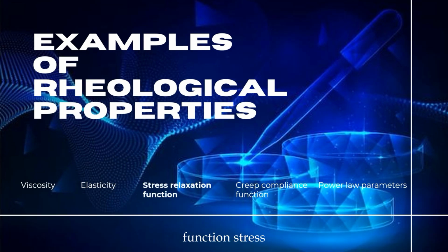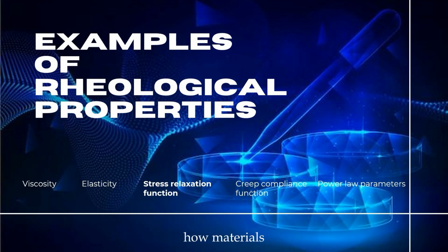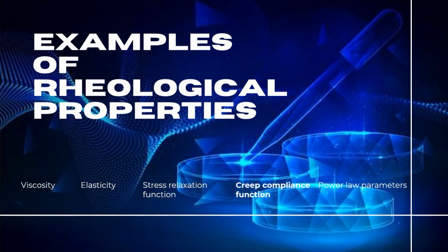Stress relaxation function. Stress relaxation is a key concept in rheology that describes how materials relieve stress under constant strain. When a material is subjected to a sudden deformation or strain and the strain is held constant, the material gradually relaxes or decreases in stress over time. This phenomenon is particularly important in viscoelastic materials, which exhibit both viscous and elastic properties.